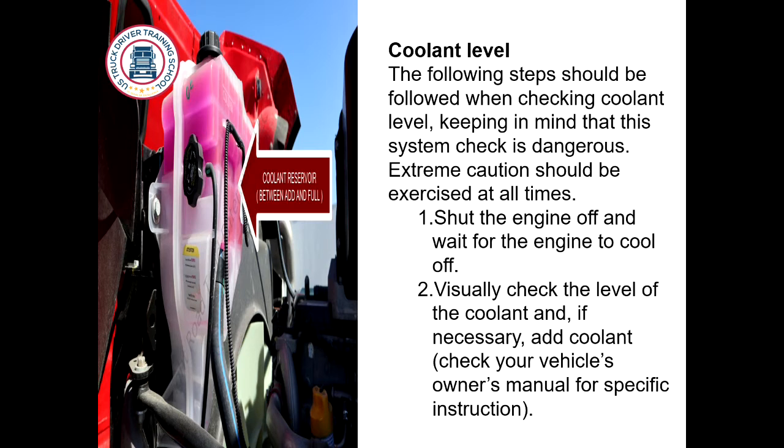Shut the engine off and wait for the engine to cool. Visually check the level of the coolant and, if necessary, add coolant. Check your vehicle's owner's manual for specific instruction.